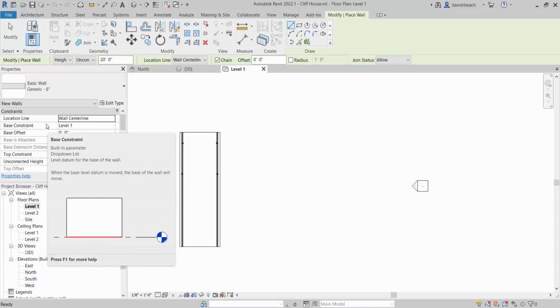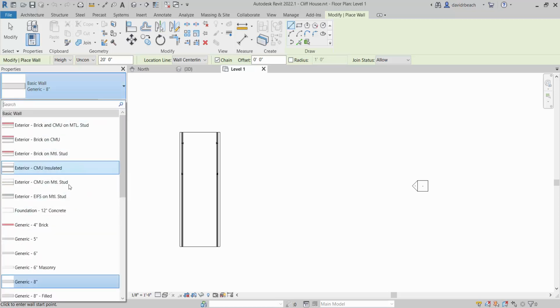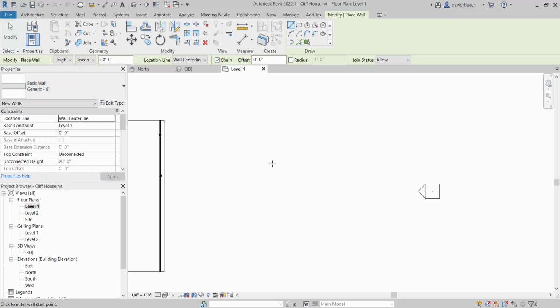So when you are learning Revit, so basically your entire academic career, I'm going to suggest to you not to use any of these complex wall types or be building any of those complex wall types. Keep it simple, so that you can focus not on managing all of this stuff, but so that you can focus on your design. So almost always, in terms of the academic environment, and really I would say more than half of the professional projects I model in Revit, I am starting with this generic wall type, right? I am working on any of these generic wall types, right? So a generic 8-inch thick wall, a really good place to start, okay?